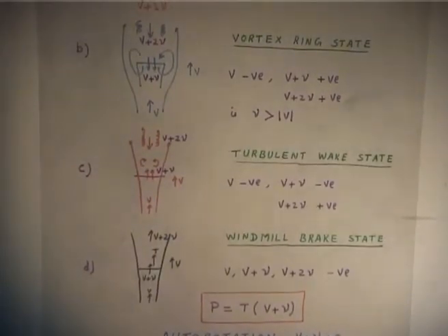Okay. So, momentum theory is not valid, but we need to have some theory, otherwise how will you calculate? So, that we will derive, then there is an approximation made mostly in tests, and then they will draw the diagram and take it as some straight line, something like that, and then say, okay, use this for autorotation, that is all. If somebody asks what is the inflow, you just say, okay, take this value, that is all. You can't calculate the inflow in autorotation. You have to have an approximate theory. Even some publications are there, experimental tests, trying to fit a curve through that and then come up with something,